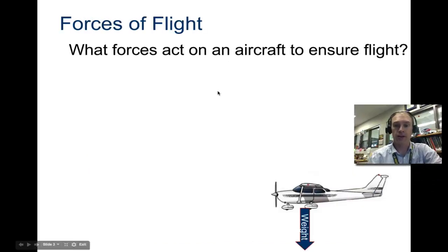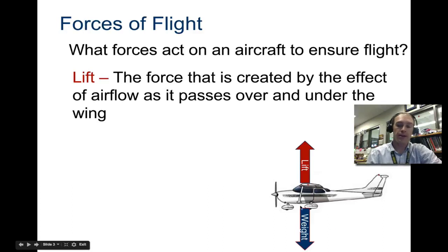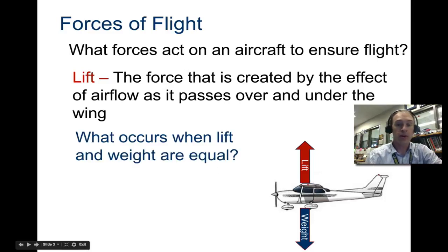Forces in flight. What forces act on an aircraft to ensure flight? You automatically have the weight of the aircraft. Lift is a force that is created by the effect of airflow as it passes over and under the wing. So remember from our discussion on what creates lift, it's going over the wing and it's going under the wing, because as it goes over, Coanda effect holds it to the top of the wing and then pulls the air down.